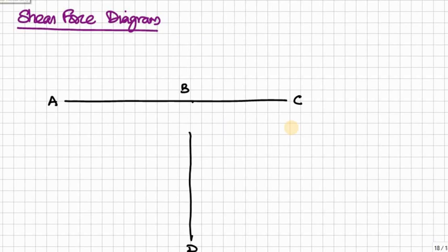Next, shear force diagram. So draw the beam ABC, and at support A we have an upward force, therefore 6.79, and there is no load between A and the point load, and under the load it drops to 10 kilonewton.